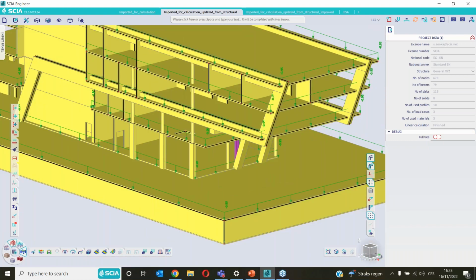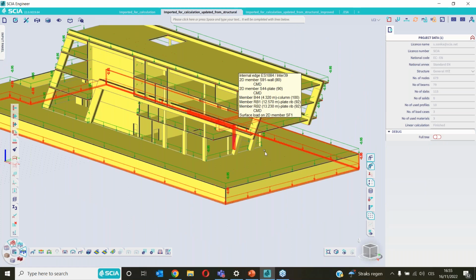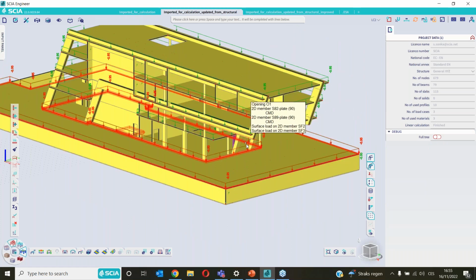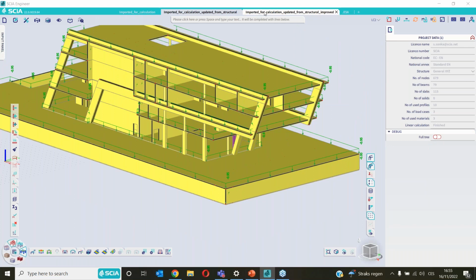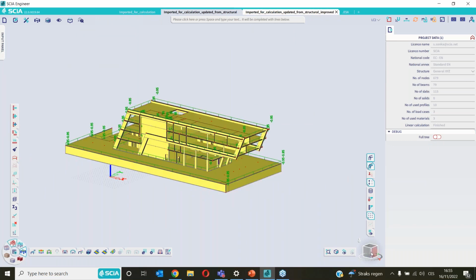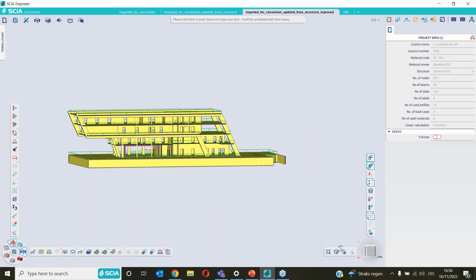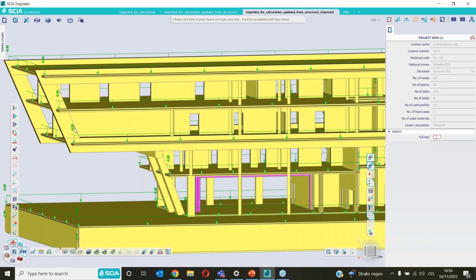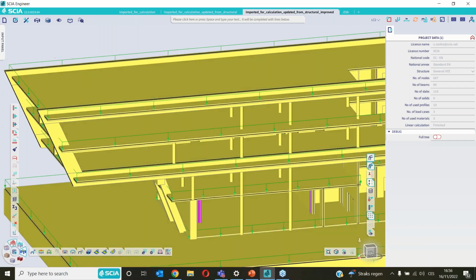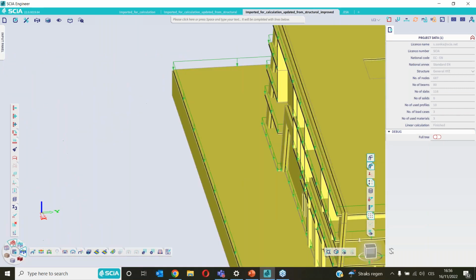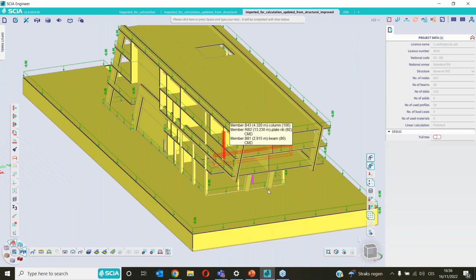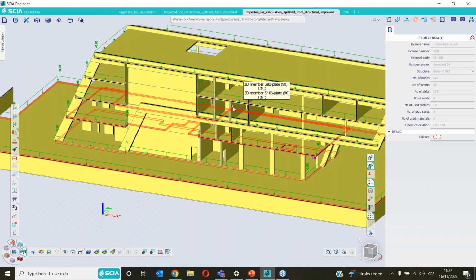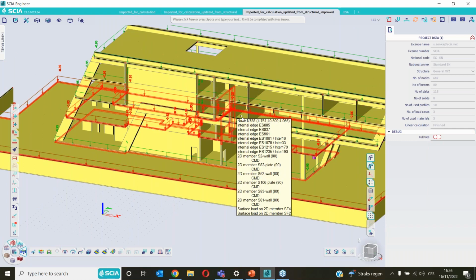And what we can do after that, maybe we can try to help that cantilever part to reduce the deflections. So I have the last model, that's this one. In this model, I have added something and changed something. I have added this wall inside the cantilever part. I have changed the cross section of this column. I have added 2 extra columns in the cantilever part, so it's this one and also 1 column on the other side, this one. And I have deleted 1 column from this area of the building.